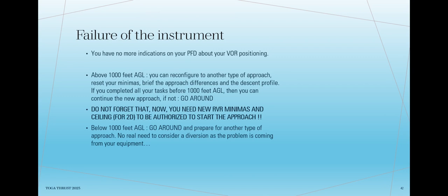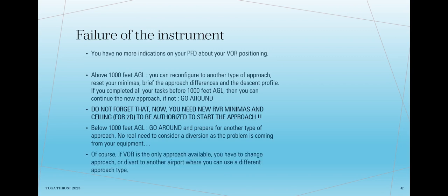No real need to consider a diversion as the problem is coming from your equipment. Of course, if VOR is the only approach available, you have to change approach, or divert to another airport where you can use a different approach type.